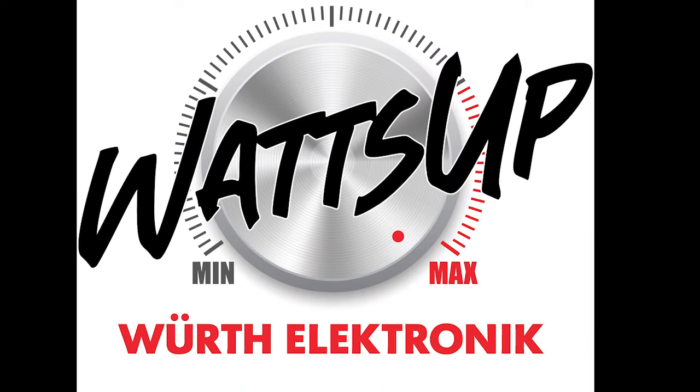With the ripple current factors 0.2 to 0.4 selected as 0.2 and 0.3 in this example, the output inductance is the operating current of the circuit to be supplied. Standard values for the inductance can be selected on the basis of the calculated value. Now, if you get the value of 37.36 microhenry as the result, you would typically select the standard values 33 microhenry, 39 microhenry, and possibly even 47 microhenry just for testing.